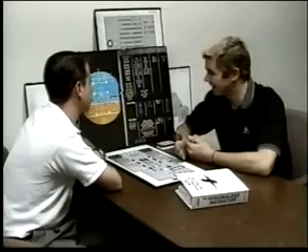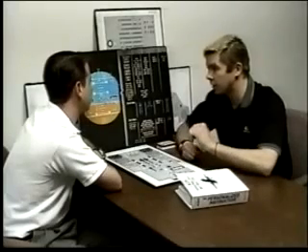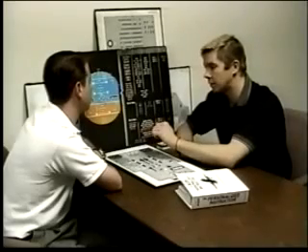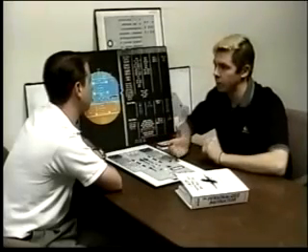How would you get rid of TOGA lock? Well, the mechanism by which you disconnect TOGA lock is just disconnecting the auto thrust. But we have a technique of moving the thrust levers up to the TOGA detent, disconnecting the auto thrust, and then moving the thrust back to wherever we want. We typically finish it off by going to the climb detent and getting the auto thrust on.